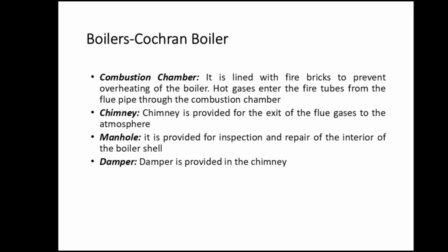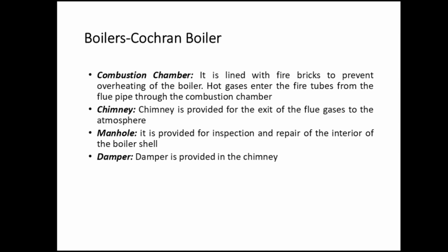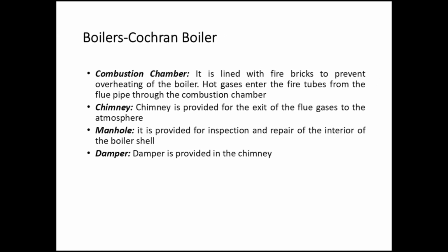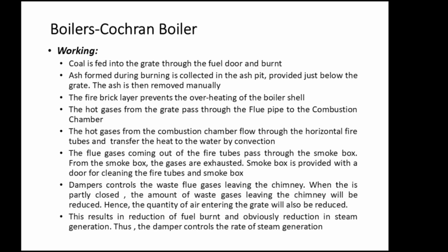Boilers, Cochran boiler, combustion chamber. It is lined with fire bricks to prevent overheating of the boiler. Hot gases enter the fire tubes from the flue pipe through the combustion chamber. Chimney. The chimney is provided for the exit of the flue gases to the atmosphere. Manhole. It is provided for inspection and repair of the interior of the boiler shell. Damper. The damper is provided in the chimney.